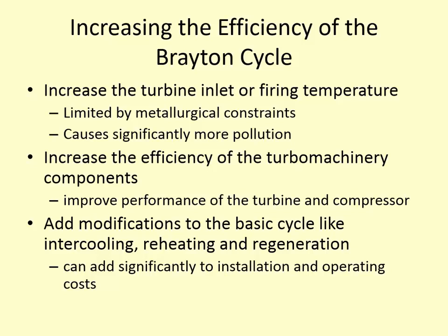But it adds significantly to installation, but also the maintenance and operational costs. Because if you have 10 turbines instead of 1 turbine, because you have reheat and regeneration in between the cycles, it's going to be a little bit more complicated to operate. If one of those components goes down and takes your system offline, it's a significant cost expenditure. So again, there's that balance of trying to make it more efficient, more effective, versus easier to operate and maintain. There's always that balance.